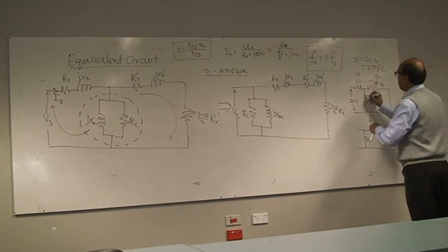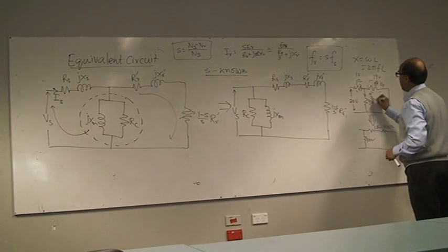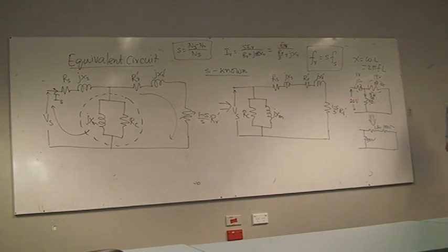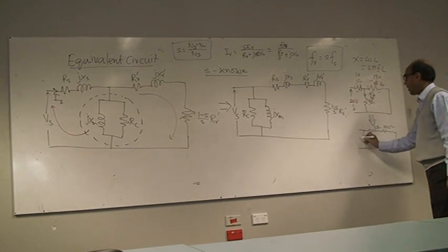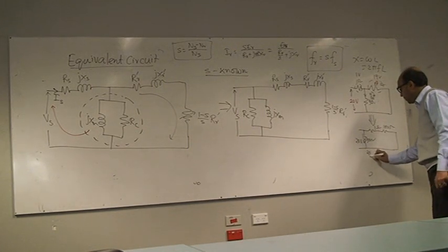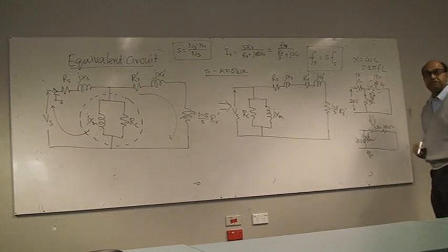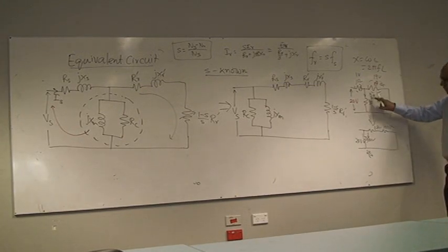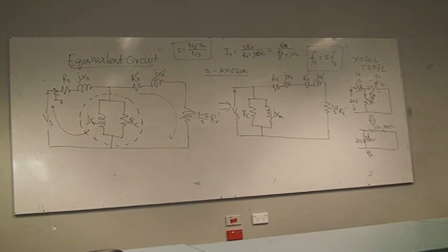So then in this 50 ohm you will get 19 by 50 ampere of current, isn't it? Now you do here, you have got 20 volt. So how much current you will get? 20 by 50 through this, isn't it? 19 by 50, 20 by 50, how much is the error? Is that 5%? So anything below 5%, engineers are very happy. So think of, we are not physicists, we are engineers. So anything that is below 5%, I ignore.